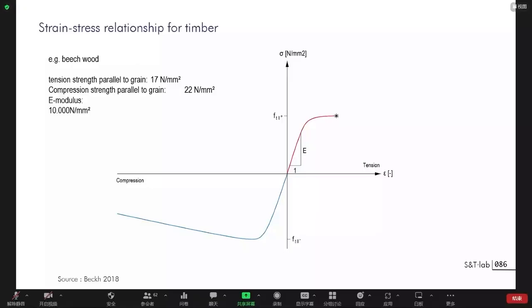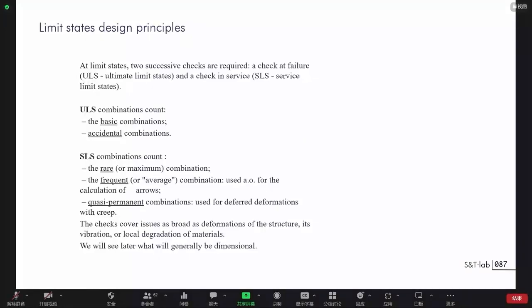And if you are designing the structure, you have to be attentive to the capacity to redistribute forces, and even more if you are working with plastic design, as we do. So the plastic possibility to redistribute force would be linked to the properties in compression or the properties you can deploy at the place of the connection, and I will be discussing this.